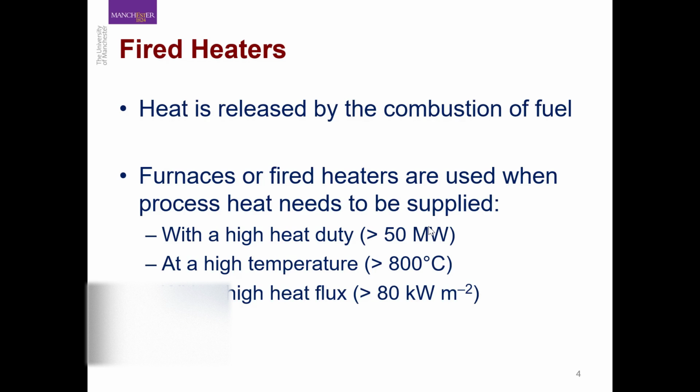There is a very small difference in terms of application, but in terms of the design or the basic fundamentals, they are the same. So fired heaters are mostly used when you require a very high heat duty, as you can see, above 50 megawatt, or you need a very high temperature in the range of above 800 degrees centigrade, or you need a very high heat flux. It means that you want much more heat transfer per unit surface area, or you want a significant amount of heat transfer, but you want to keep the surface area minimum. So these are some of the basic factors or features that dictate when we require a furnace or a fired heater.